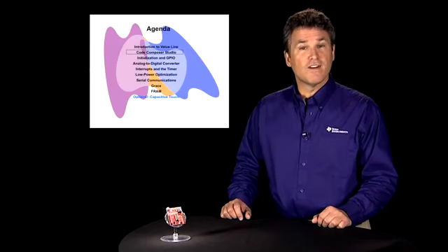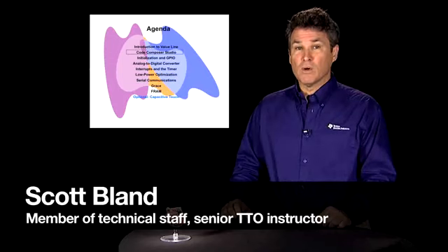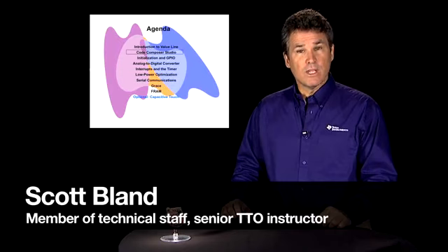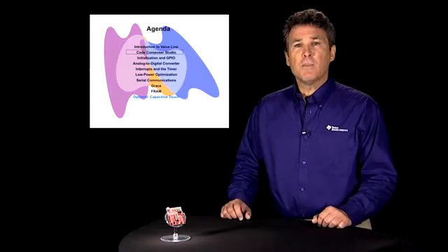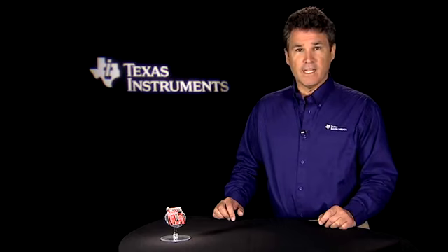Section 2 is an introduction to Code Composer Studio version 5.1. Code Composer is an integrated development environment, or IDE, that combines the editing, debugging, and analysis tools into a single package. It's based on the Eclipse open source tool. Before you can write code for the MSP430, you need to get acquainted with the tool that you'll be using. The MSP430 is also supported by IAR's Workbench tool, which is a fine IDE. But the labs are all written to use Code Composer, so let's get started with that.